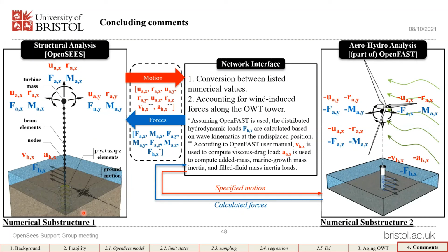Yeah. Okay. And what about the wind load? Did you apply along the length of the tower? So yeah, the wind loads along the length of the tower, the magnitude is significantly lower than the concentrated force of the turbine. So it is a predetermined, uncoupled series of distributed loads.